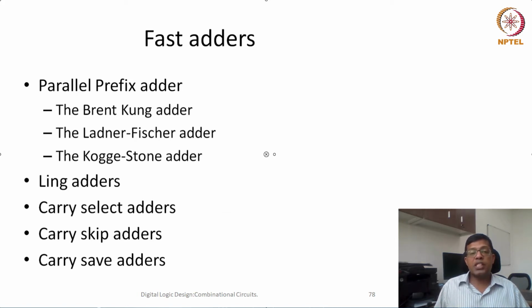There are various combinations people have thought of and created. Some of the popular ones are Brent-Kung, Ladner-Fischer, or Kogge-Stone. Ling adders are also sort of parallel prefix adders. These parallel prefix adders are variations of carry look ahead in a more general sense, where the combination of how the carry would be generated in a look ahead manner is slightly different in each of them, and each would have one advantage or another over the others.